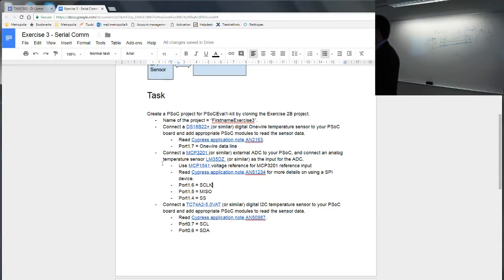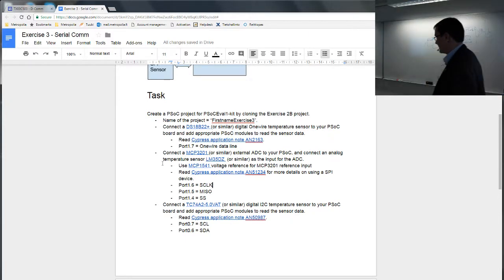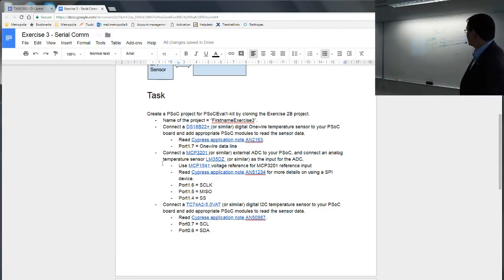The point is not to put everything there and start wondering why nothing works, and then find out that the LCD module actually requires lower than 12 megahertz CPU. I found it out yesterday. So if you are using LCD, use CPU speed sysclock divided by 2. It doesn't work at 24 megahertz CPU speed because the delay is done by NOP operations in assembly code. It's a software kind of module.